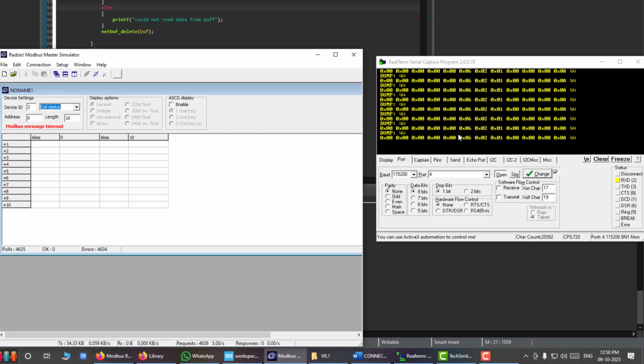So we are confirmed that this is a standard Modbus RTU packet, but with some header prepended to it, that means in the beginning. Let us see what these extra bytes are. From here to here, 1 2 3 4 5 6, we have 6 extra bytes.